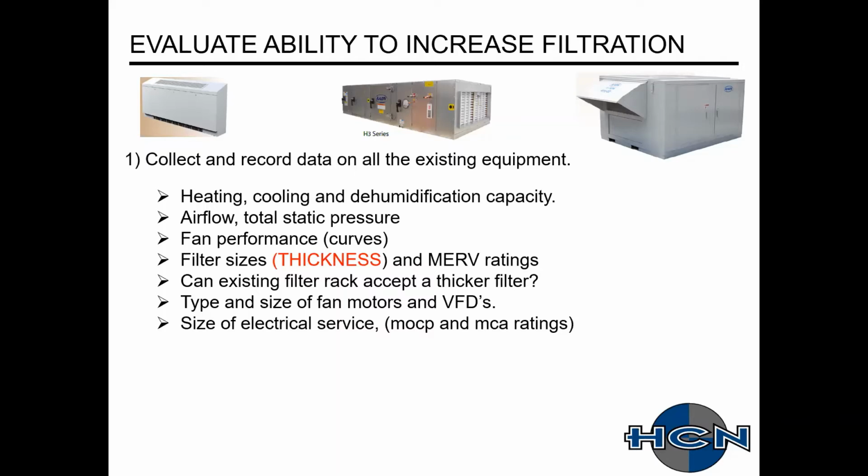For your filters, what's your MERV rating? What is also the thickness? And then, can the existing filter rack accept a thicker filter? You should look at the type and size of your fan motors as well as VFDs. And then you should also record your electrical service, related to your refrigeration circuit, but also related to equipment for your